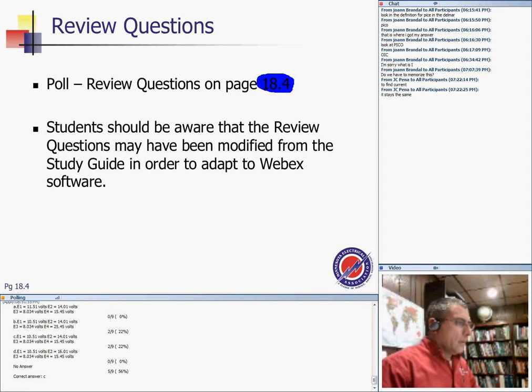I'm going to emphasize question number 11 in particular, and how to use the voltage divider. You can find the voltage across every resistor by taking the resistor value, dividing it by the total resistance, and multiplying it by the source voltage.